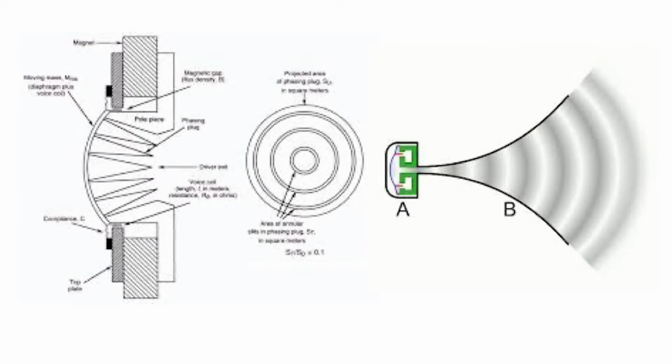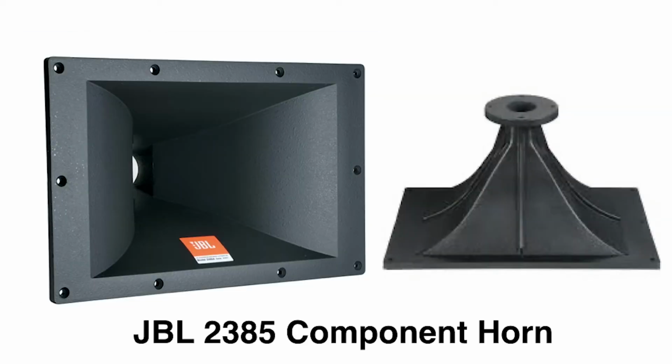Most professional speakers that are intended as PA speakers do not have tweeters, like your typical studio monitor or a hi-fi speaker might. Instead, the majority of common speakers you will find have a woofer and some type of horn, with what is referred to as a compression driver attached to the back of the horn, to deliver mid-range and upper frequency information. A simple tweeter is not nearly efficient enough to use as a high-frequency component in a main PA speaker enclosure. Thus, a compression driver/horn combination is used.